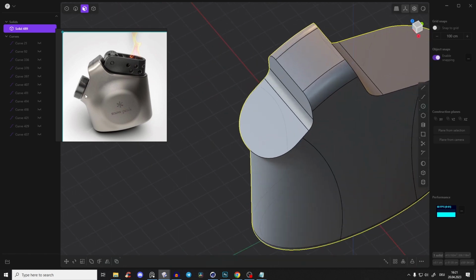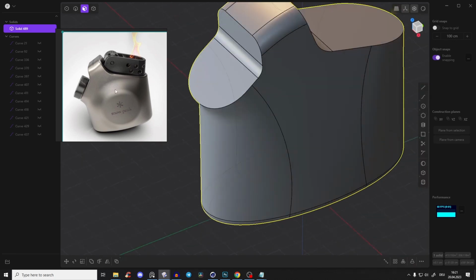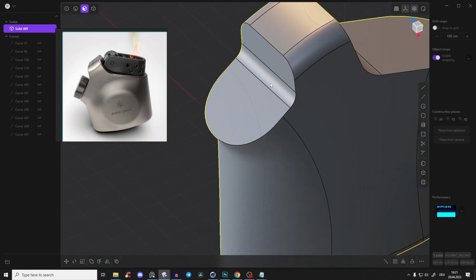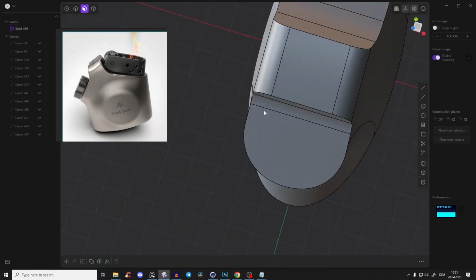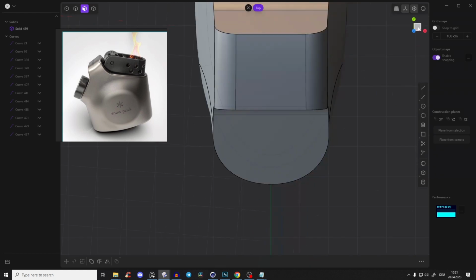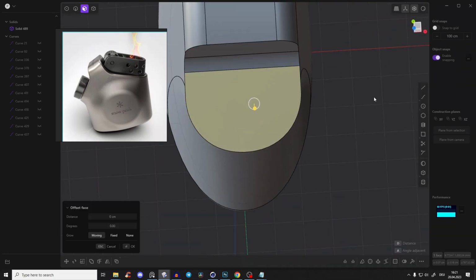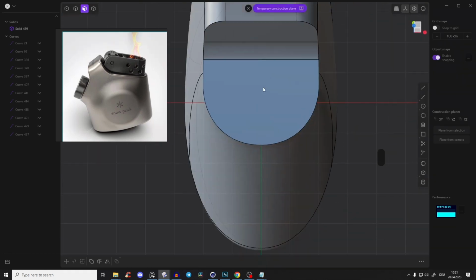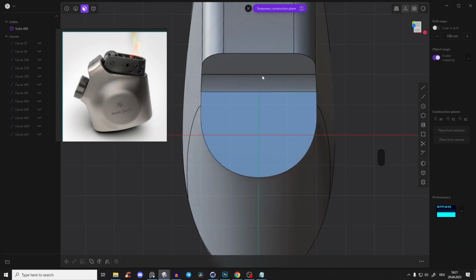And now let's create this little knob here, and then we will create this detail. And at the end, I also struggled in the beginning to figure that out, so we can create the circles. So stick to it. And here again, that's what I said. If we select this face here and press spacebar, we have a construction plane, and we look at it straight.